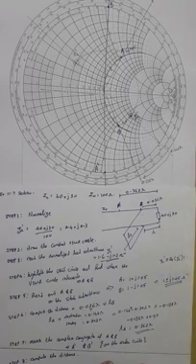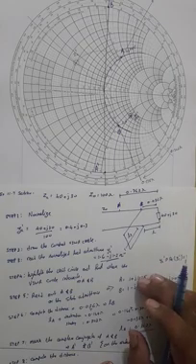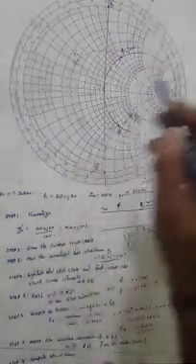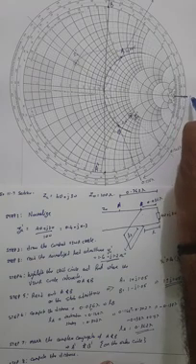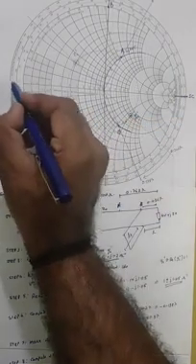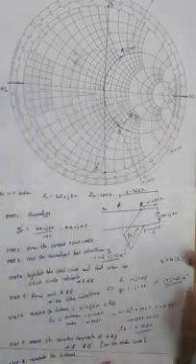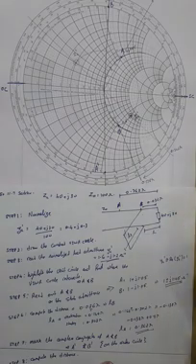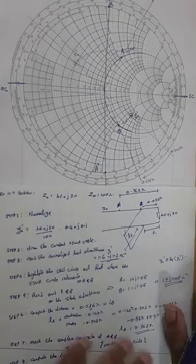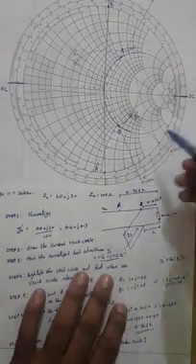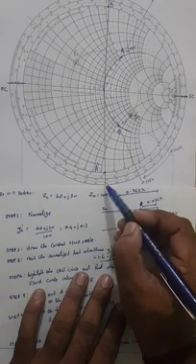You'll have to make one more assumption. You'll have to check if you have a short circuit stub or an open circuit stub. Now on your admittance chart, the rightmost end over here is going to be your short circuit spot, and the leftmost end over here is going to be your open circuit spot. Now since in this question we have the short circuit spot, usually we will be using short circuit stubs. So to compute the distance, you'll have to measure the distance from the short circuit spot to A dash.